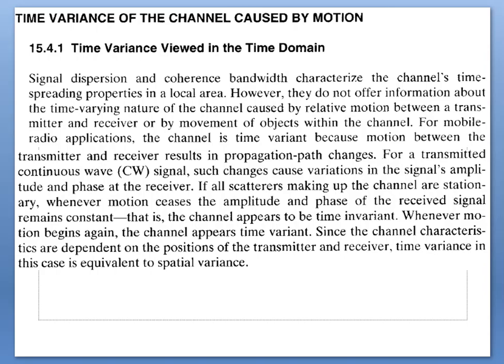whenever motion ceases, the amplitude and phase at the receiver remain constant. That is, the channel appears to be time invariant. Whenever motion begins again, the channel appears time variant, since the channel characteristics depend on the position of the transmitter and receiver. Time variations in this case are equivalent to spectral variance.